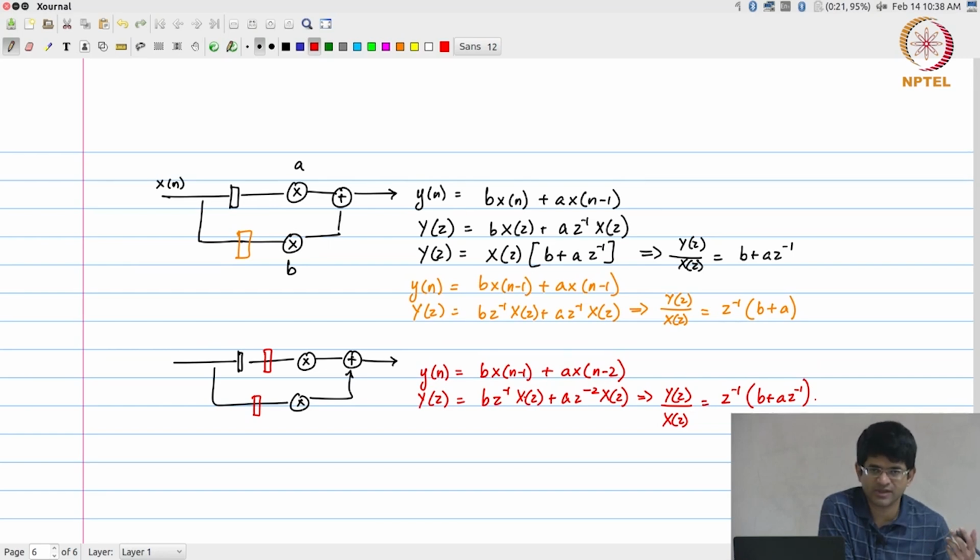In other words, if this was a low pass filter with a cutoff at some particular frequency, the third transfer function, the red one over here, would also have a cutoff at exactly the same frequency, whereas the second one would have been converted into an all pass, because there is no longer any dependency on z inverse as far as the function is concerned.